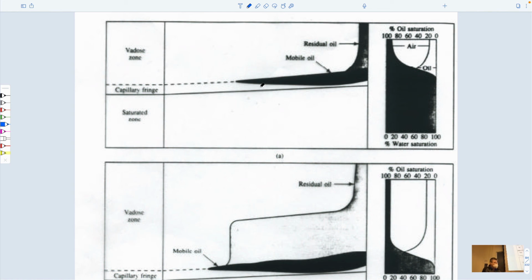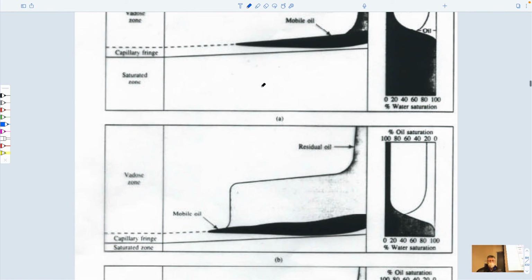If during summertime and wintertime the water table migrates, you can imagine that this shelf that the free product is floating on drops. As it drops, it will provide a smear. The smear will be on the full width of this lens that's sitting on top of the water table. So as it goes down, the smear goes down from this whole portion.